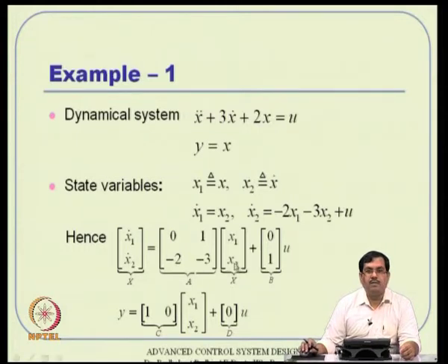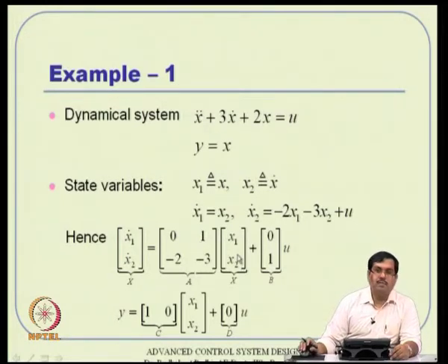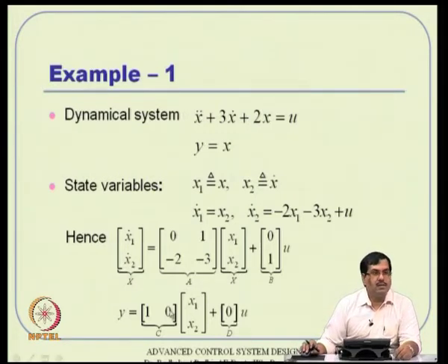The different matrix forms, whatever you come up with, they are all tied up with similarity transformation, and similarity transformations preserve eigenvalues, and eigenvalues are poles of the system. That means, the stability nature and all that are not perturbed by whatever way you write actually. So, the system variable definitions can be different, but system properties remain unique actually. That is a nice thing about this type of analysis.